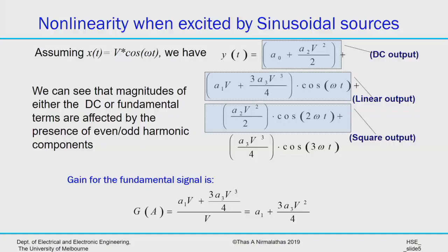And nonlinearity cannot be avoided in most RF circuits because that's the exact characteristic that we are exploiting, either in the reverse bias junction capacitance as a varactor, or a diode or a transistor as a function to frequency translate. That nonlinearity is what actually gives you that frequency translation, therefore you can't avoid it. You just need to know how to manage it.